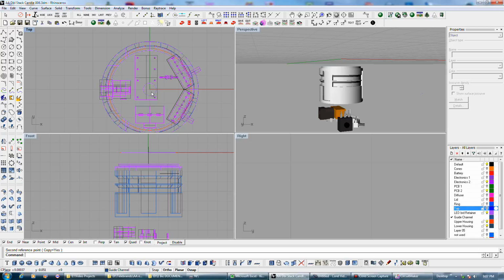So I just need 4 wires coming off and just hooking to the circuit board somewhere, and I could probably get away with doing that and just keep it off the circuit board completely, and then I gain my real estate back for resistors and so forth. So, again, those are some of the practical constraints you run into. That's why, again, drawing your components, all your fixed components, you've got to start with. That's probably what I'll do, because that's a very practical solution to this problem.